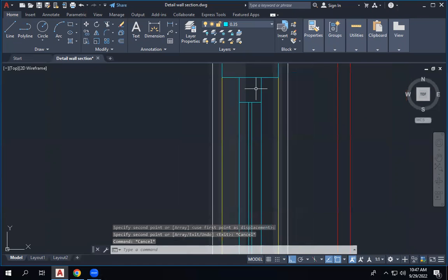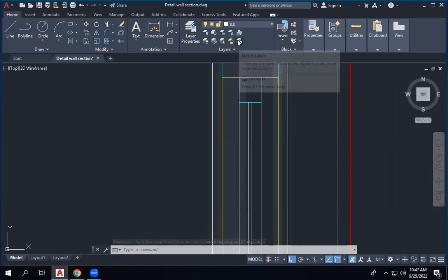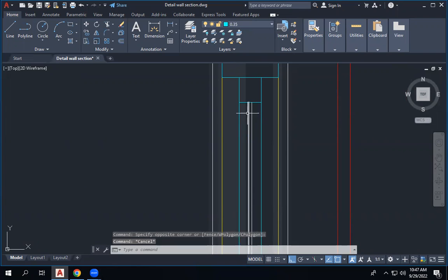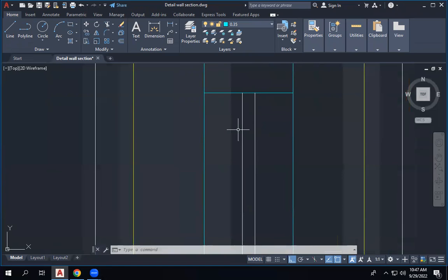So how am I going to give the line thicknesses? I will give 0 for this one, the glass, even though it cuts. If I give 0.2 or 0.1, it will be too dark. It's very close to each other, so I'll give 0. When you print it, if you see it is too dark, you can just draw one line and keep it as this. But I think it will be okay because of the scale that we are going to give this, half an inch to 1 foot. I think it won't be an issue.